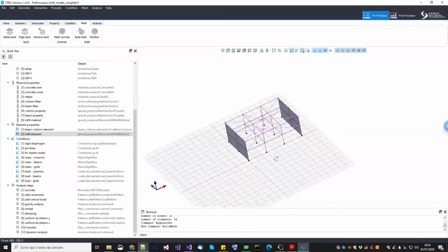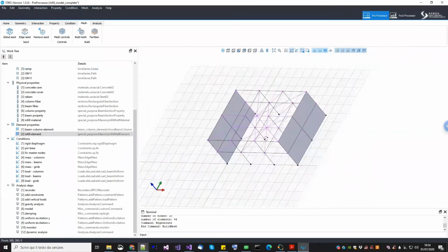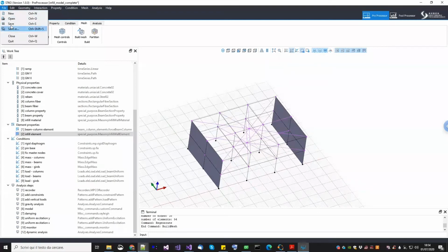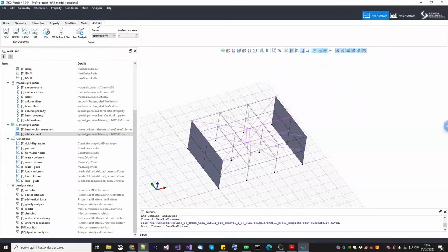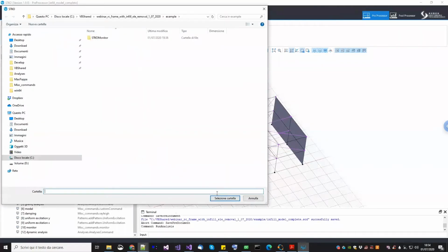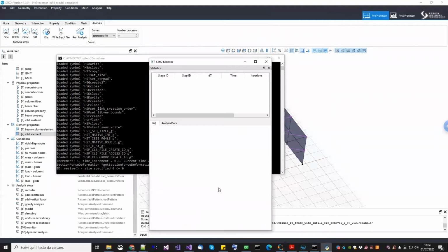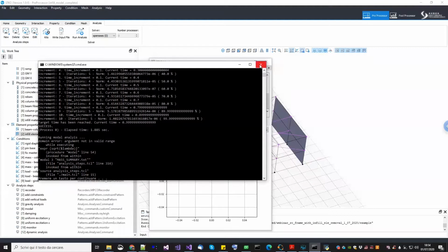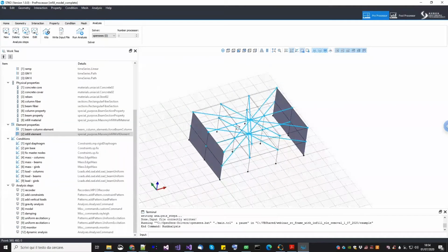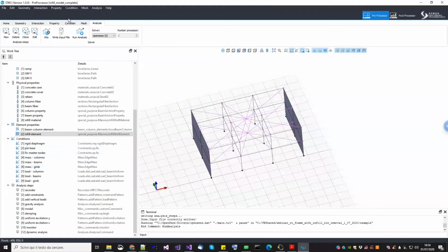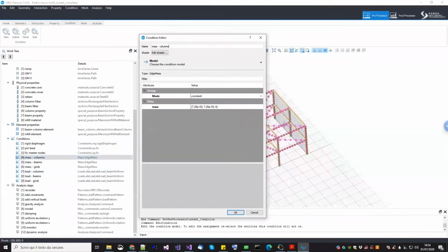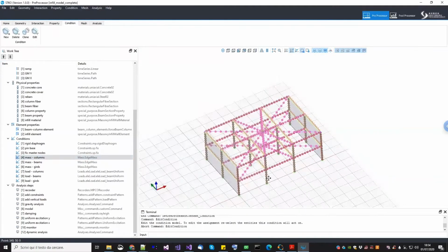So when I build the mesh now, they are just 4 node elements, not triangles, okay? So once I've done this, I can save it. And I can finally run the last analysis. Okay, here I probably made some mistake with the model. Yeah, probably I missed some of the masses here. Well, let me see if all the masses are properly assigned. Columns. Yes, probably I didn't assign them, but this is what happens.